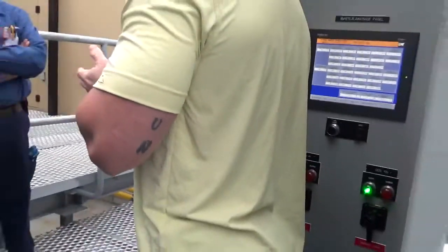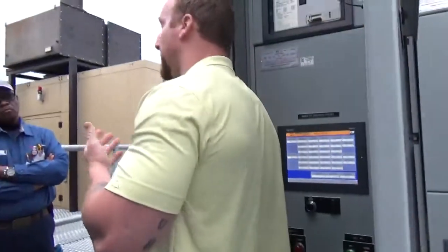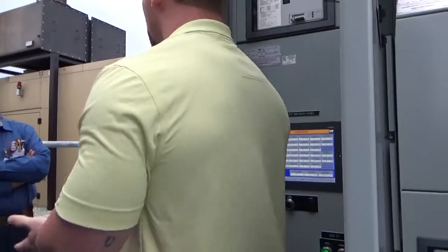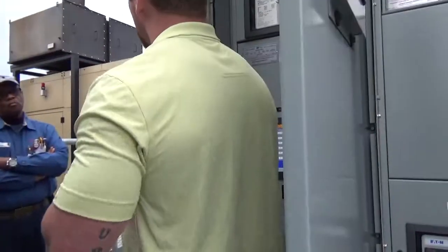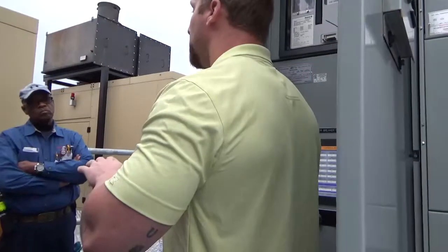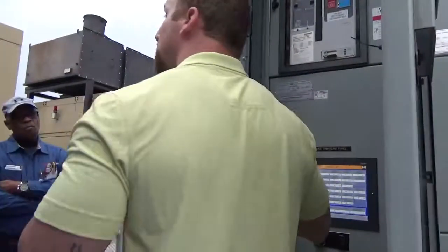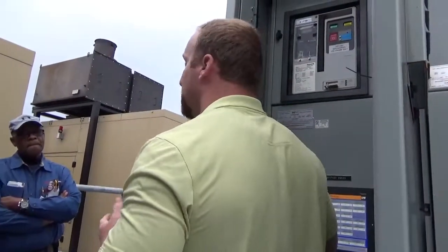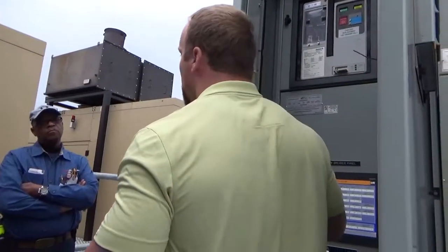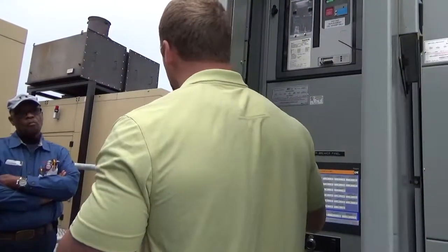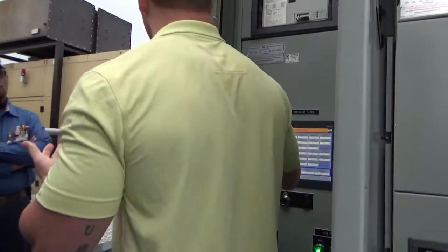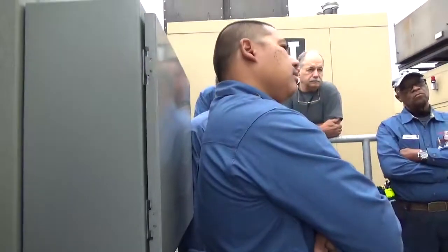So this is another feature because you do not have enough load for the site for one generator or whatever, and you have to offset that with load bank. Gen demand is a function that you have that helps with that. So when you have both gens come up, you close them both to the bus, and then the switchgear senses how much load you have on the bus, and also senses how much available load you have on the bus. Once it sees that you're not at the right percentage, it says, okay, I don't need 2 gens to run. I'm going to shut one down.